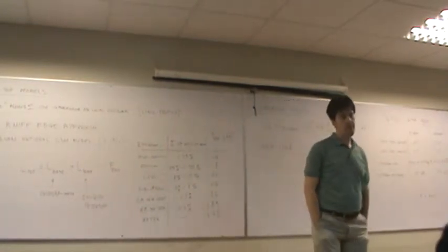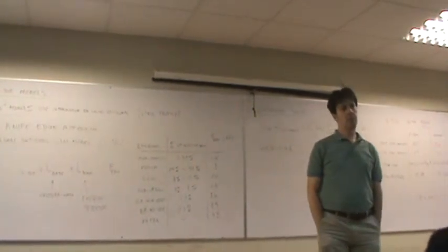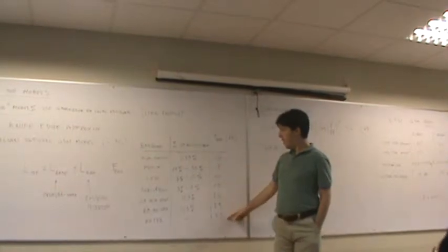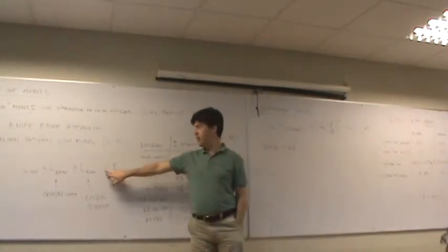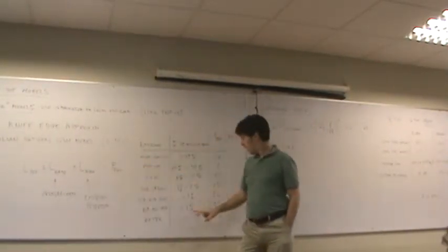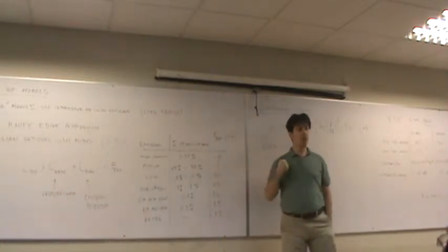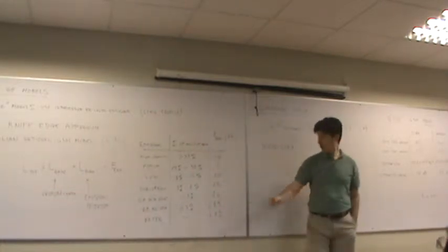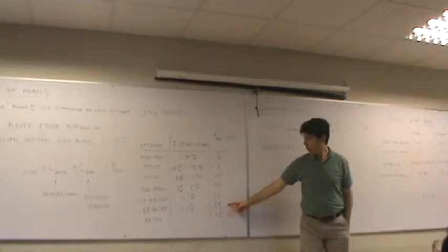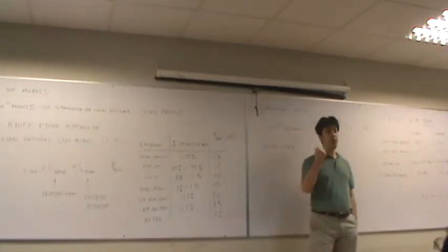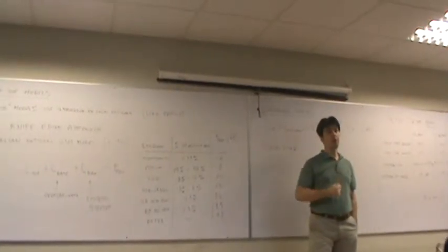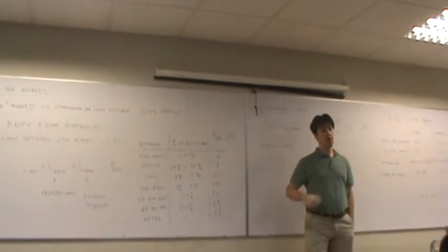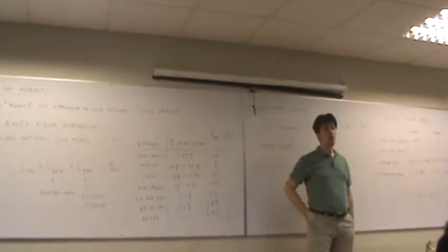But since there is a minus sign here, those values actually reduce the loss. So the losses, for example, where you have no vegetation, will be 30 dB smaller, so the signal will be 30 dB stronger than what it would be without the correction.